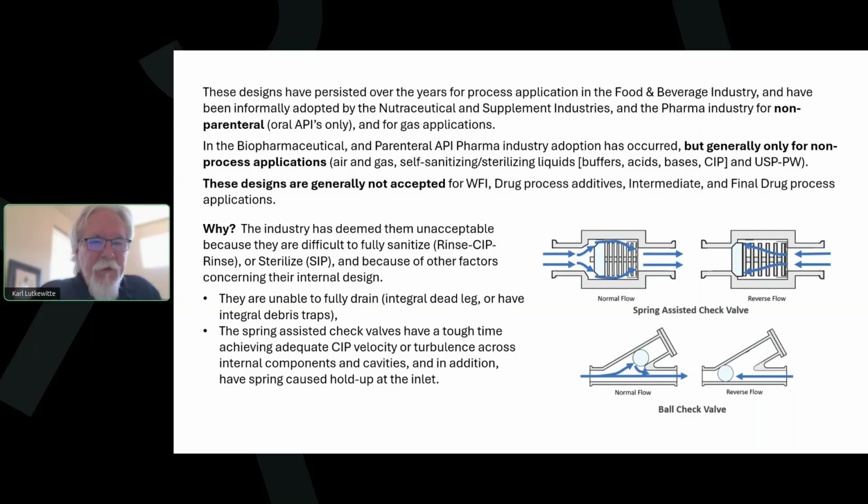The second reason is that the spring-assisted check valves in particular have a hard time achieving needed CIP velocity and turbulence across the internal components and cavities. They're tough to clean.